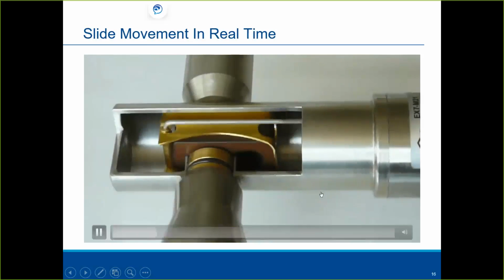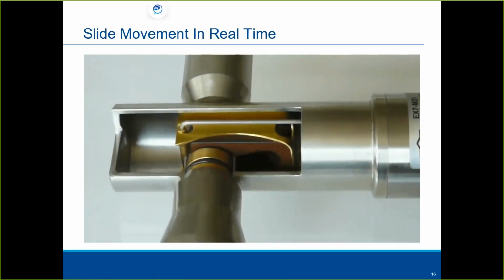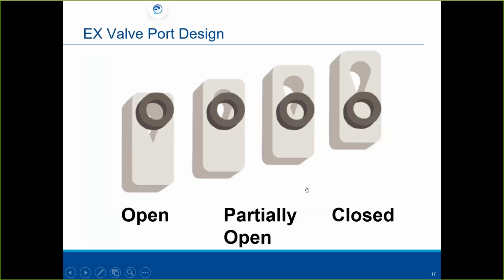Let's see if I can get this in place so you can hear it running. And this is what that looks like. All it's basically doing is sliding over in this teardrop, okay, and letting that out. And when the hole gets over, this would be open all the way. As it covers here, it blocks it off. So the more of it that's over that teardrop, obviously, the more refrigerant that's going to come through. Again, open to close in 5 seconds.